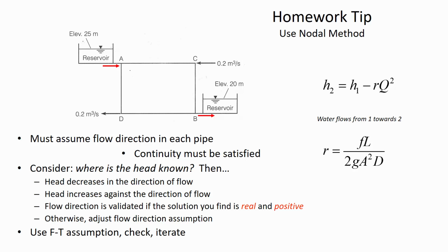You can use the fully turbulent flow assumption to begin because you don't know what the flow rates are, but then you should check that assumption to see if it's valid and make adjustments as necessary. So take a crack at it.